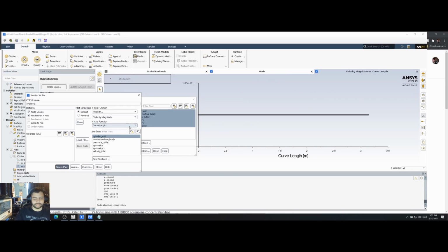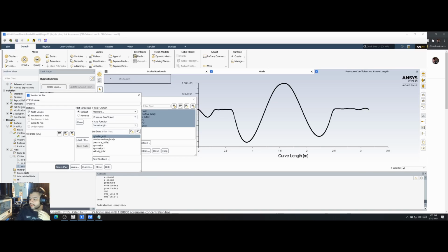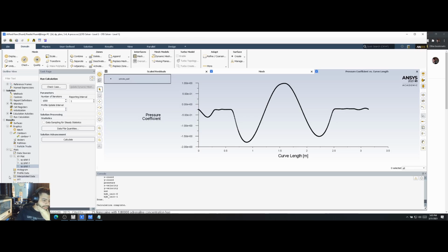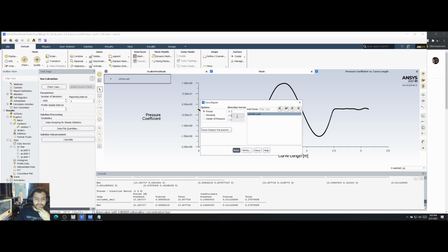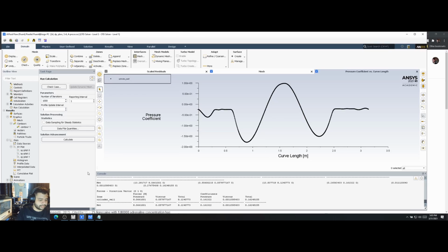We're not gonna have anything there. And now for our pressure coefficient, save and plot, and that's what we got. Now it's asking us to do the drag and lift coefficients. So we are gonna go down here under forces. This is gonna be for drag, boom, and for the lift, 1 is there and 0 here. We're gonna print that, boom, and now we just are missing the streamline.